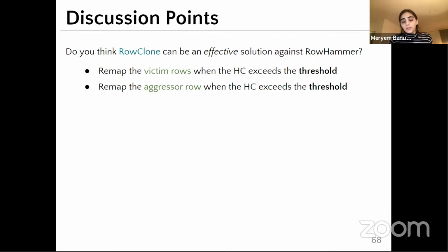Well, I was thinking about something like that, but in that case you interfere with the other scheduling policies implemented in the memory controller, right? For example, if you limit the number of activations to specific rows, maybe the memory scheduler is doing something to optimize fairness within the scheduling policy, but then you interfere with the policy. But if you just remap, I think refresh is also in the same track. If you just do something within the DRAM, you don't have to interfere with anything in the memory controller. But I agree, this is also a potential track.